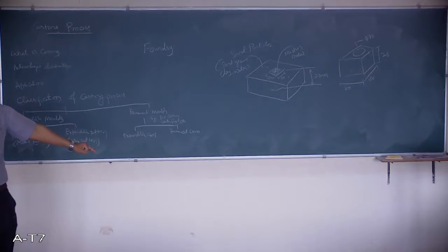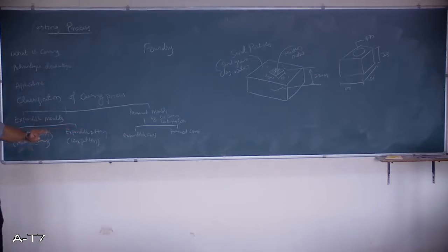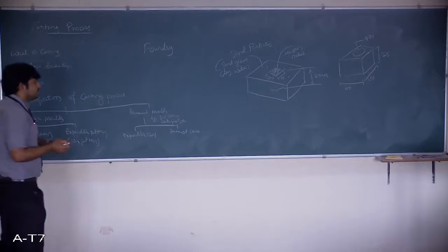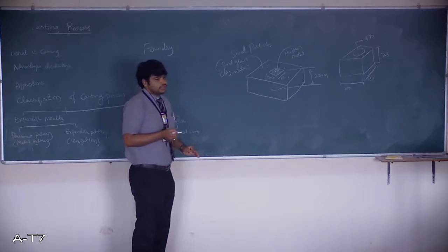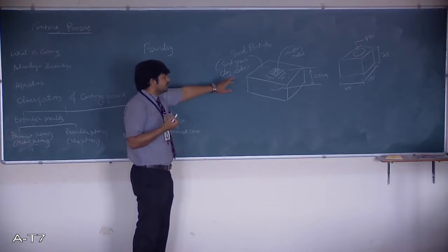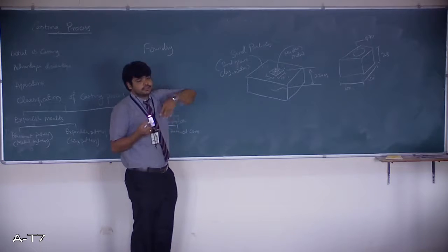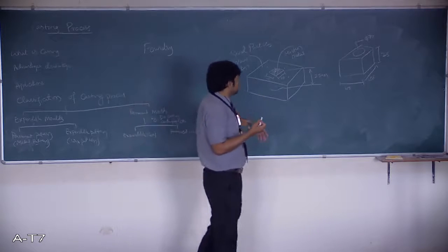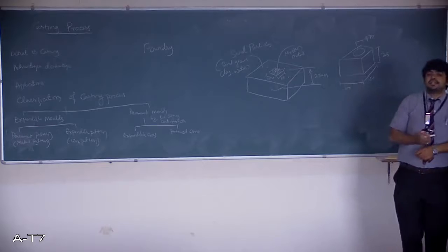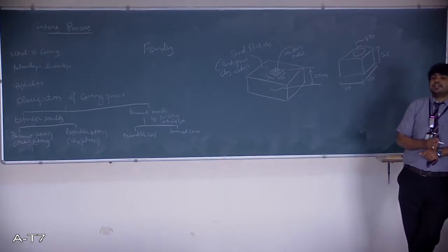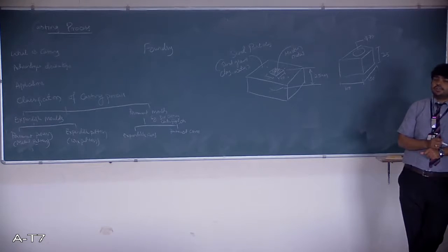Second one is, it is not eco-friendly in most cases, as gases are going to be generated because of the solidification of the metal and also because of the burning or combustion of chemicals due to the elevated temperature of the molten metal. If we make use of chemical binders, or in case of clay and water, they are also going to generate gases during solidification or when they come in contact with the high temperature molten metal.